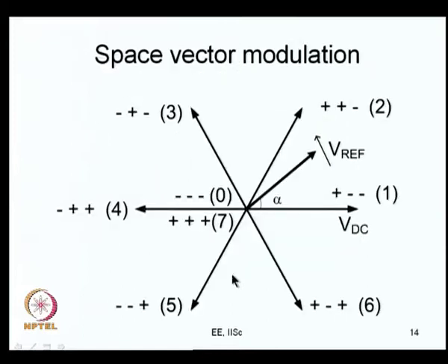And so, with that model, let us say the PWM inverter has been switched using space vector modulation. As we have been seeing in the last several lectures, space vector modulation basically means a voltage vector is provided instead of 3 phase voltage references, and the voltage vector has a certain magnitude Vref, which is proportional to the desired fundamental voltage, and it is revolving at a constant frequency, the desired modulation frequency.